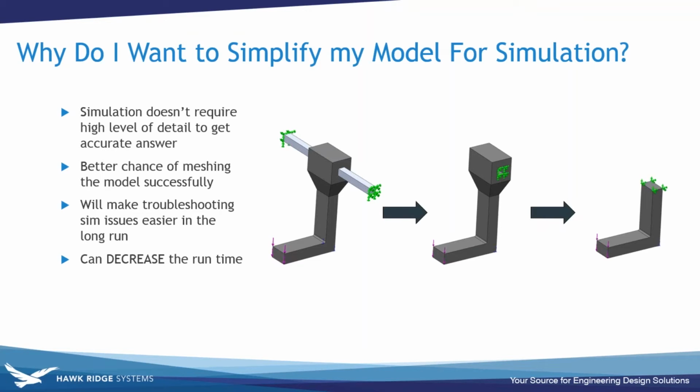So the more detail you have in your model, the more time it's going to take to filter out what the root cause of the issue is of meshing your part, or maybe even running the analysis. Maybe the level of detail is so complex that we're not going to be able to account for all the components that are there, and at the end of the day, we may not even need any of those components or a lot of the components.